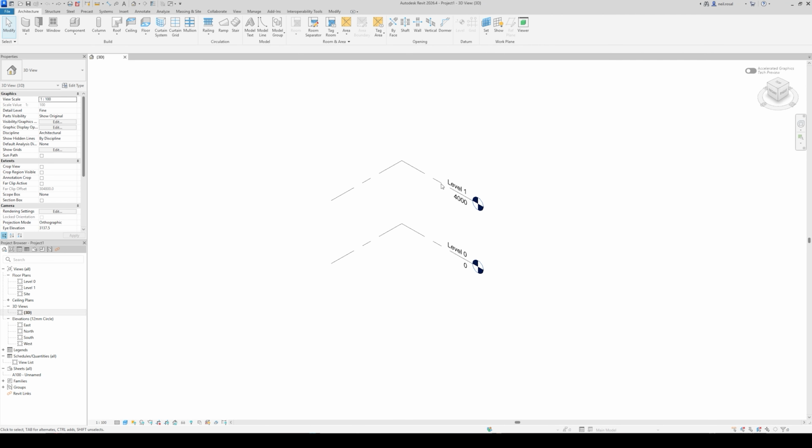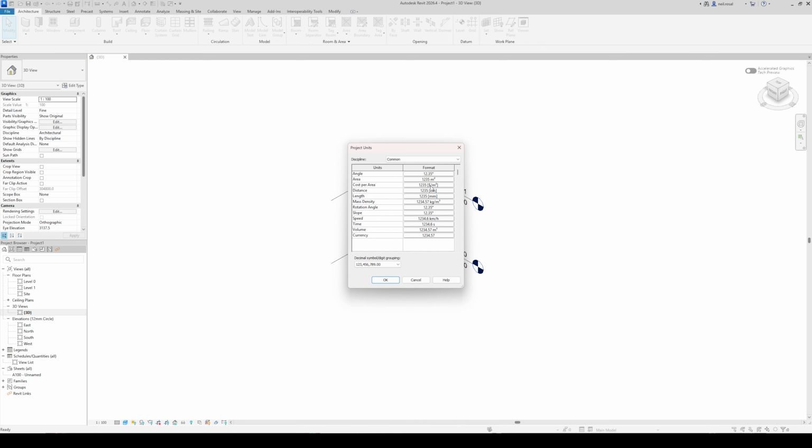So what I want to do first is usually to set up my file in the beginning to double check if I'm working in meters, because that's how I usually work, preferably. I'm just used to Rhino and working in meters when I'm modeling. So to do that, we're going to type in UN. It immediately does a shortcut when you type in UN. As you can see, this is in centimeters and millimeters, depending on the template, as I mentioned earlier, but we can always change that over here in the units section.